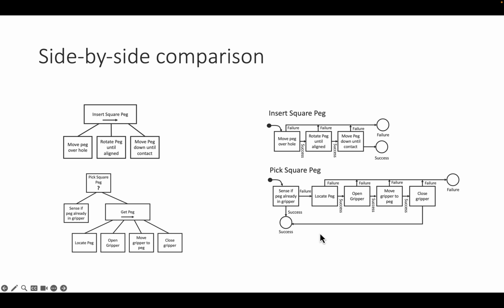Now again, you would never program the majority of these possible failure modes when you write a finite state machine in the first place. Why would you? Instead you would run into those only as you start deploying your algorithm and testing it. So here behavior trees help you to think about your problem in the right way.